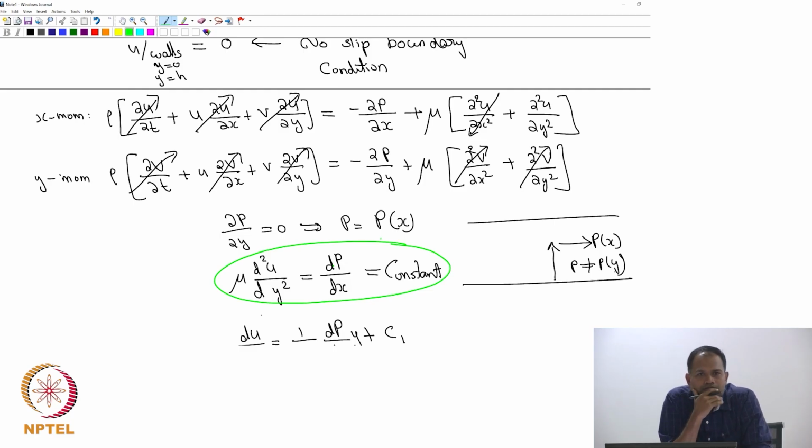And yeah. So, why do we neglect the gravity in the momentum equation? Right now I am looking at a pipe that is actually perpendicular to the gravity. So, the only thing that would have happened is that there can be hydrostatic pressure that is perpendicular to this.